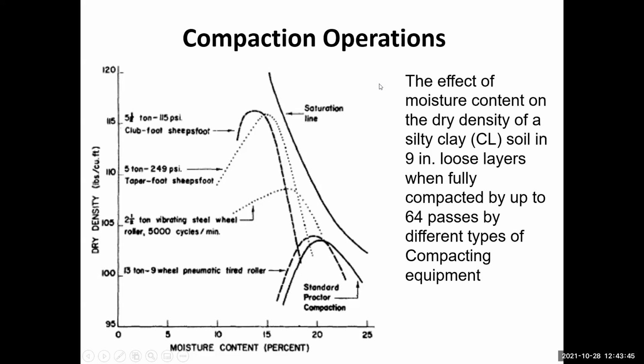The main purpose of showing these curves is that it is sometimes very difficult to achieve in the field the same moisture content as in the standard or even the modified Proctor test.